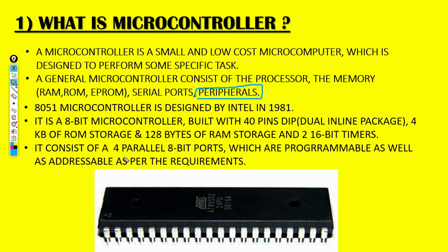So 4 parallel 8-bit ports simply means that we have 4 input-output ports through which we can transfer or receive data, which are of 8 bits. They are programmable as well as addressable, which means we can program the input-output ports, or we can use them as input port or output port, whichever is required from us. We can use them in both ways.